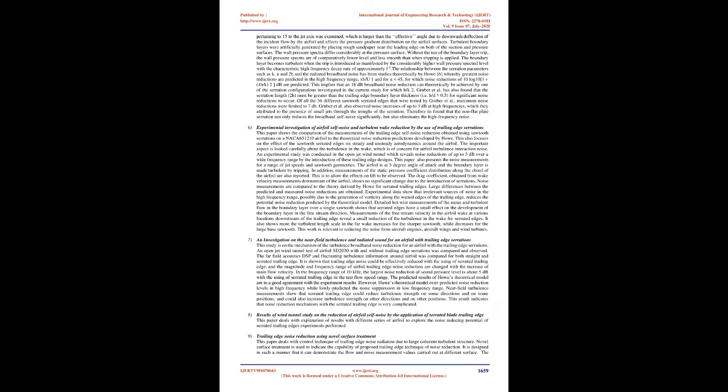In this study, airfoil self-noise pertaining to 15° to the jet axis was examined, which is larger than the effective angle due to downwash deflection of the incident flow by the airfoil and affects the pressure gradient distribution on the airfoil surfaces. Turbulent boundary layers were artificially generated by placing rough sandpaper near the leading edge on both of the suction and pressure surfaces. The wall pressure spectra differ considerably at the pressure surface.